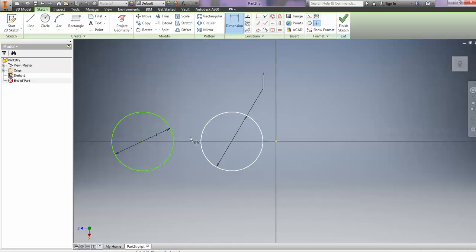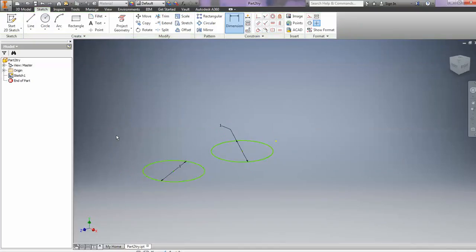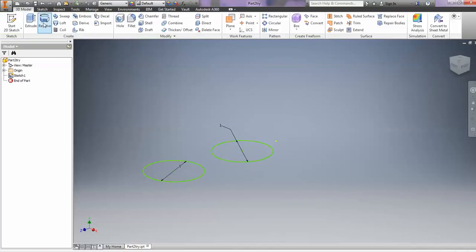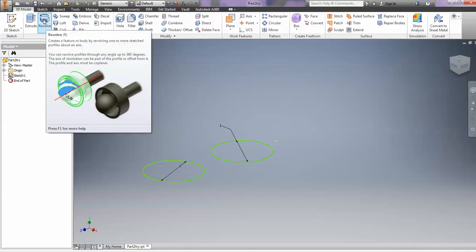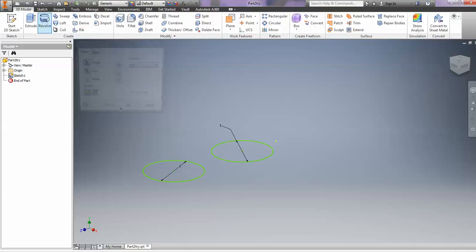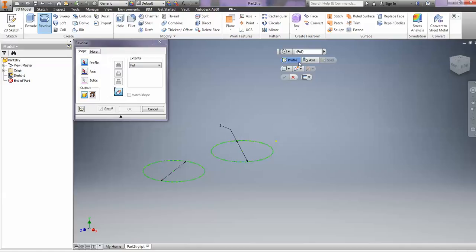Now just using those two circles, I'm going to finish this sketch, a very simple sketch. Immediately I'm going to go across into 3D model, and I can start playing around with some of these things here. We can revolve things, or we can extrude. Let's just revolve this for a second. We haven't got a profile. Let's do it by an angle of 90, direction 1, axis.